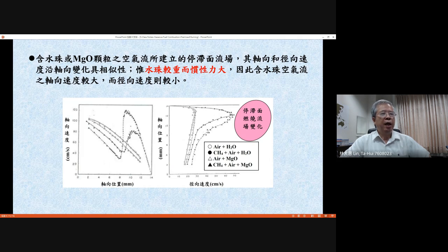Later on, this actual velocity, the flow velocity, will face the rear stagnation plane, the coast plate, then it will be reduced because of the influence coming from the stagnation plane, reducing to zero here. Okay, this is the typical actual velocity variation. Actual velocity means the velocity direction points to the flange surface. It's perpendicular to the flange surface.